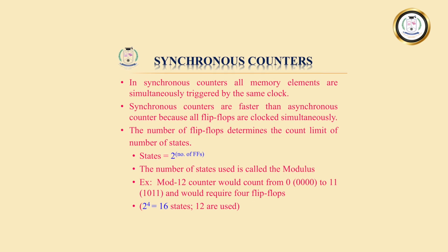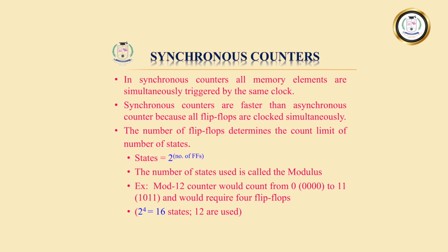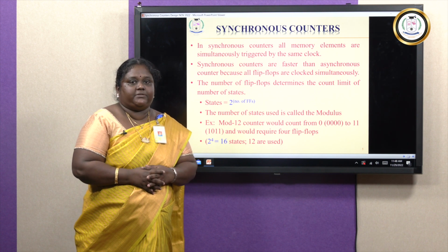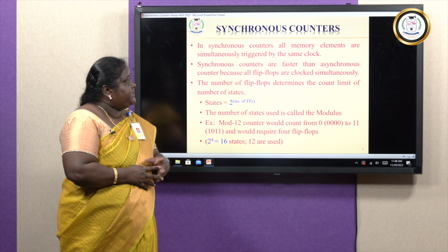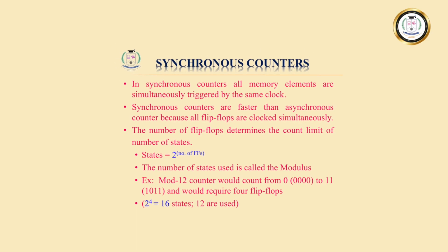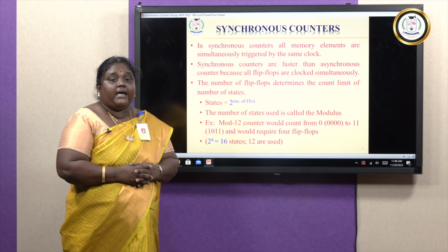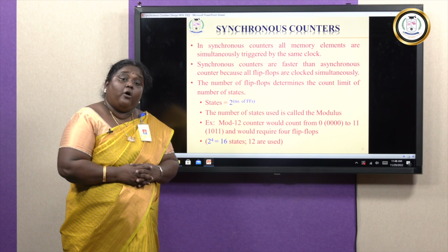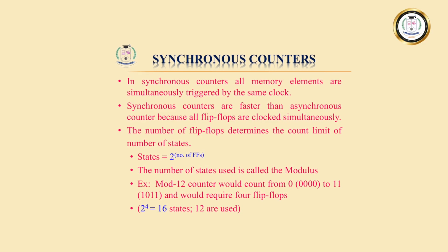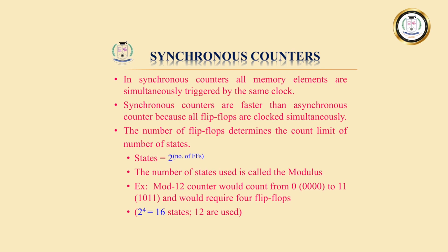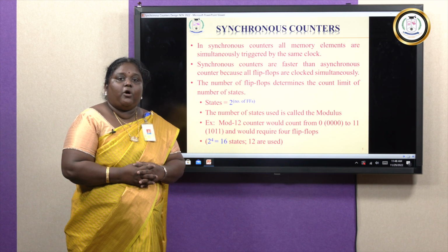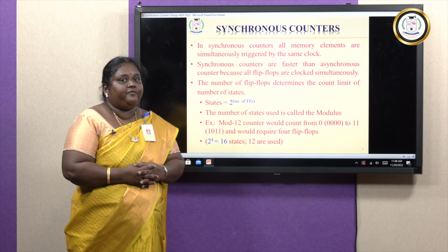Next, let's get started with the synchronous counter design. Before that, let us understand what a synchronous counter is. Synchronous counters are counters that are triggered simultaneously by a single clock pulse. That is, a single clock is applied to all the flip-flops. As discussed earlier, synchronous counters are designed by connecting flip-flops in a cascaded fashion, and a single clock is supplied to all the flip-flops.